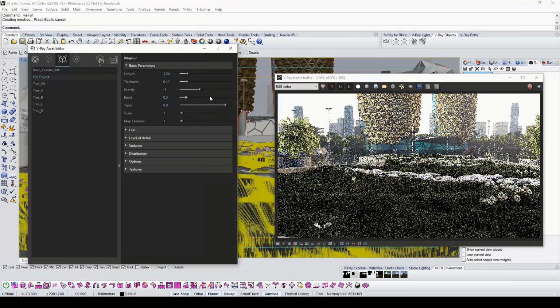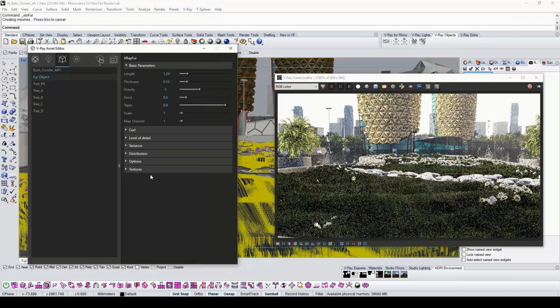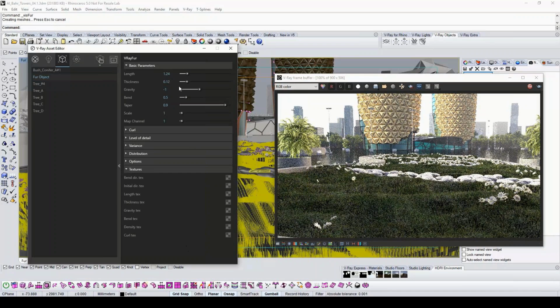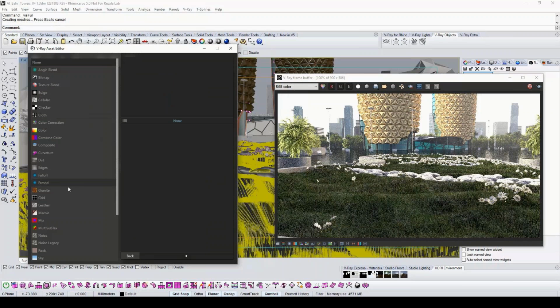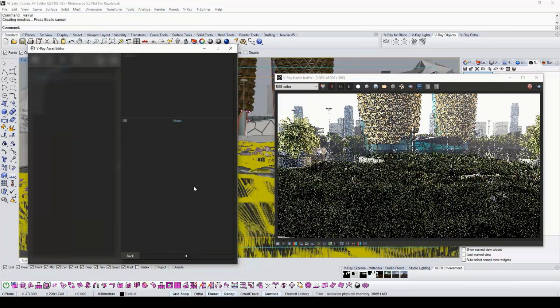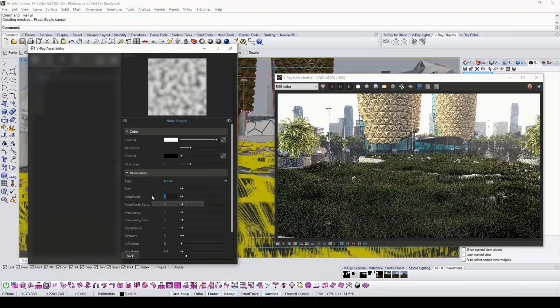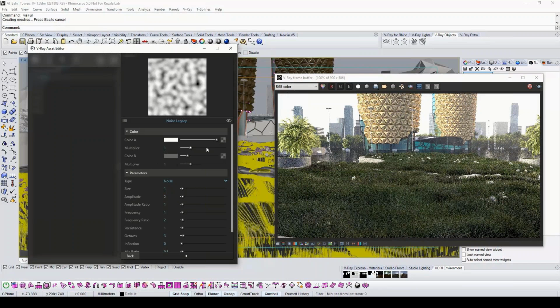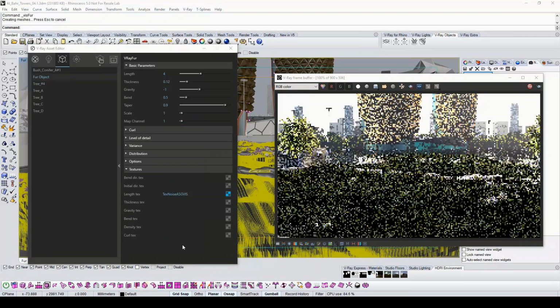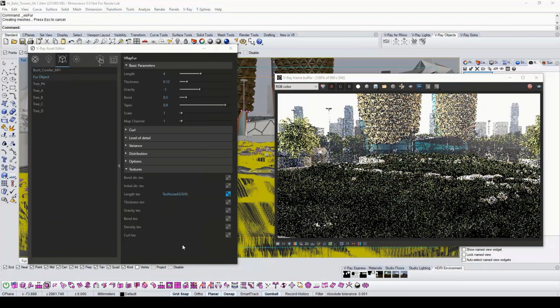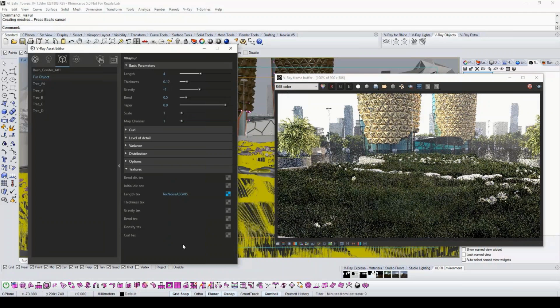Now let's say I'd like something a little more natural looking with clumps of grass that's longer and shorter, and what we have is the ability to use textures to affect different parameters. So what I'm doing now is I'm going to create a noise texture. And what this is going to do is everything that's white will be the maximum, which I set back to 4, and everything that's black would be a length of 0. But I used a light range between white to a dark gray, and you'll notice now there's clumps of grass which are longer and some clumps of grass which are shorter.